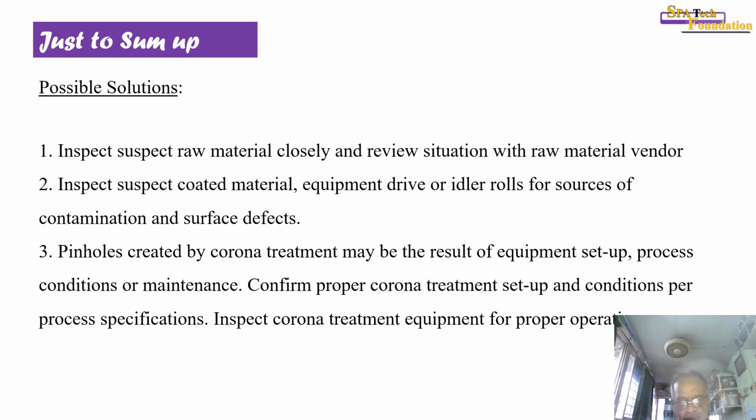Pinholes created by corona treatment may be the result of the equipment setup, process conditions, or maintenance. Confirm proper corona treatment setup and conditions per process specification. Inspect corona treatment equipment for proper operation. Also inspect the corona treated surface by using corona checking solutions which are readily available.